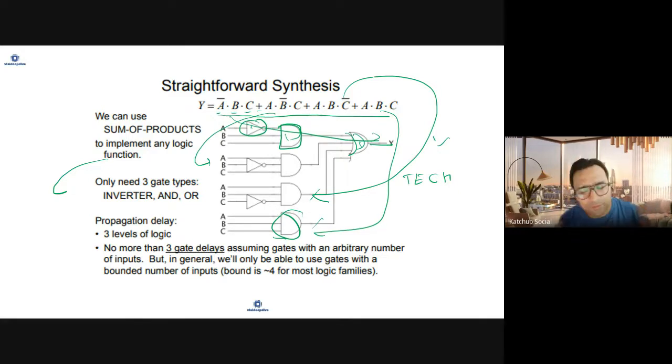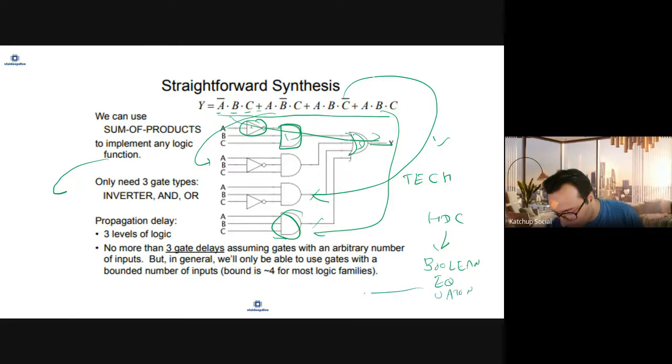But if you think of the first step, simply thinking, your design or HDL is converted into what is known as Boolean equations, and those Boolean equations are, say for example, in sum of product form, and these are then simply converted into gates, which is the synthesis. Of course it's a complicated process, but just to understand the principles, we're taking a simple example.